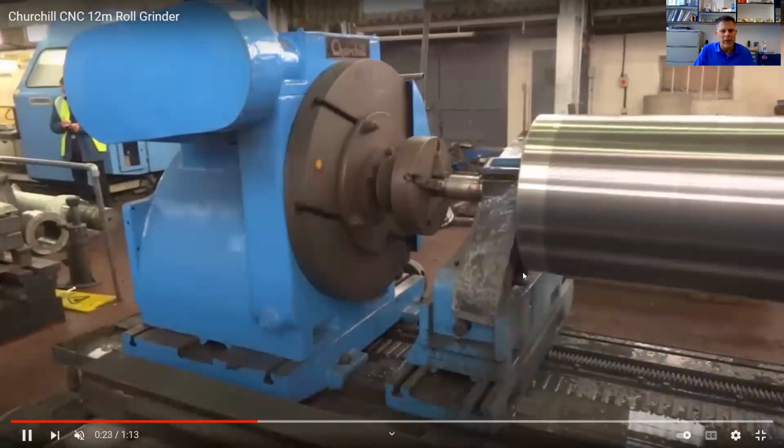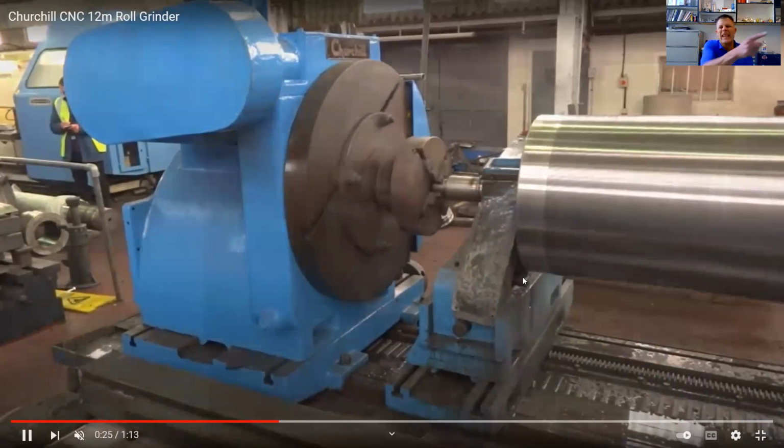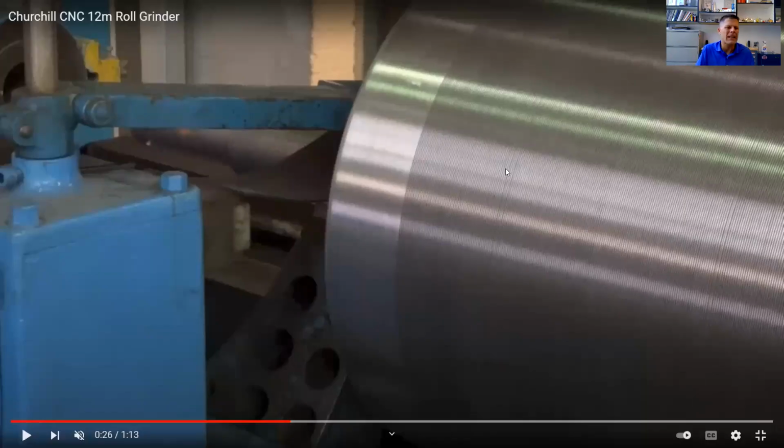Because if you think about it, the surface finish the lathe leaves is a helix as it's coming down your part. In fact, I paused the video. You can see the surface right here ran a 76 thou chip load, if you remember that video. That means every revolution, the tool moves 76 thou forward. So there's a 76 thou helix spiraling down that part. And if you're going to use that to maybe roll something out, like roll sheet metal out to a correct size, you want a smooth surface finish. So the traditional processes couldn't create that smooth surface finish.